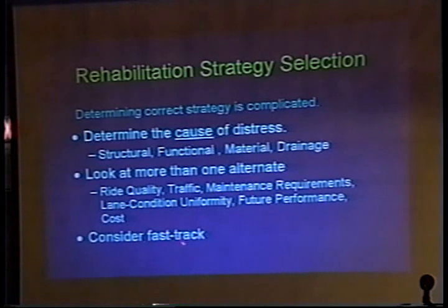One thing you do want to consider is utilizing some of the more up-to-date and newer fast-track methods for concrete pavement that are available. Full depth repair, partial depth repair. We have some good additives for concrete that can be added in for allowing a quicker set time and higher strength gains in the early stages. Not just your typical MS and FS mixes that ODOT specifies, which may set up and not give you enough time for actually finishing the pavement, but other additives that are available. And I think Jim Barnhart with High Ready Mix will get into some of those proprietary products.